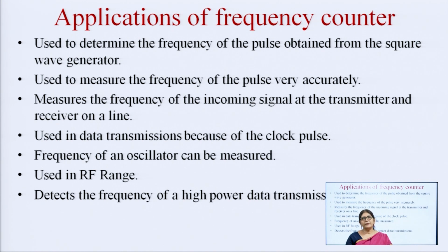Now, applications of the frequency counter. We can use these frequency counters to count the number of pulses in data transmission. They are also used for measuring frequency very accurately, and to measure the frequency of an oscillator. If we have designed an oscillator and want to ensure that the frequency generated is the same as what we designed, then we can measure it with these counters. They also detect impulses or high frequency signals in a transmission line, and can detect those pulses.